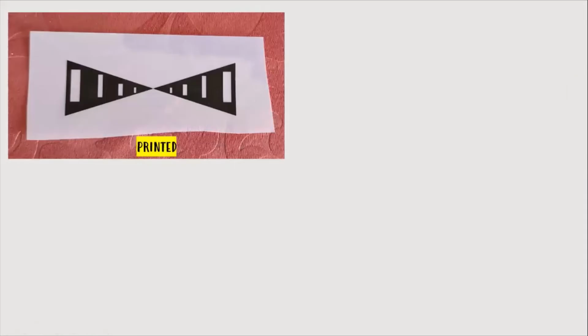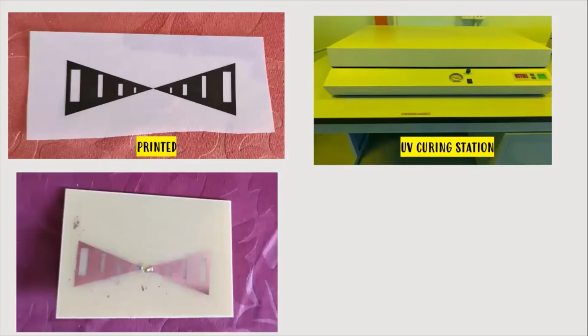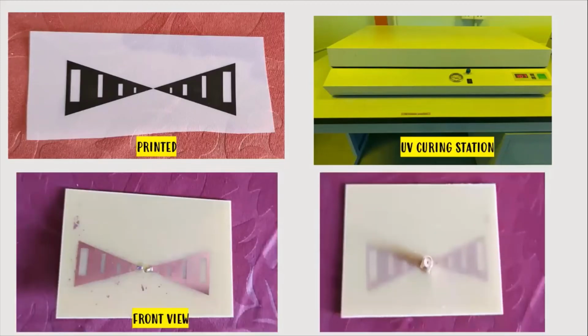Okay, the first one is the printed version, where it uses matte paper, printed from a normal printer. Okay, it's black and white ink because this is what we will transfer to the PCB UV board by using the UV curing station. This printed version will be placed on the PCB UV board, and then we will insert it inside the UV curing station for it to transfer the image to the board. And this is the end result, the look of the fabricated antenna.